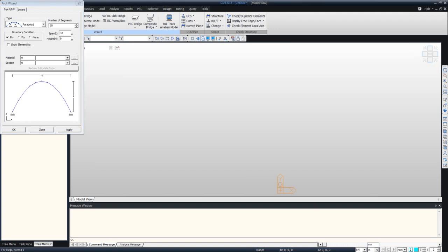So if you need to change your units at any time, just go to these drop-down menus. And as you can see, you have everything from meters, inches, feet, etc. So you can model your project in either SI or English units. Same with your load properties, or your weight properties, excuse me, your weight units. So we'll keep it in meters and kilonewtons for now.